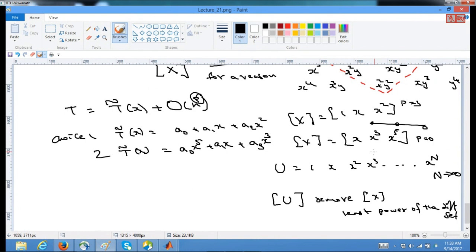That means, if I have a mesh size of h, and I decrease the mesh by half, then my error is h to the power of p. So this would be h by 2 to the power of 3, since p is 3 here.